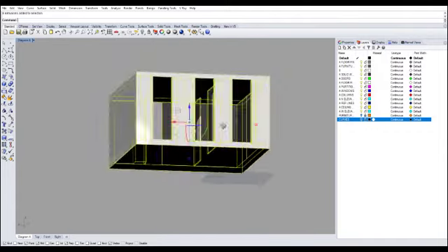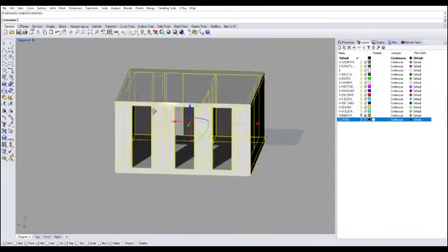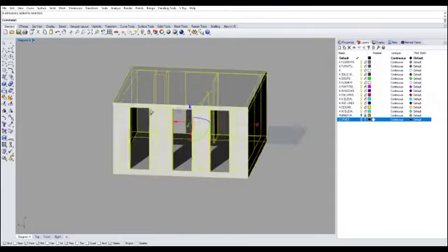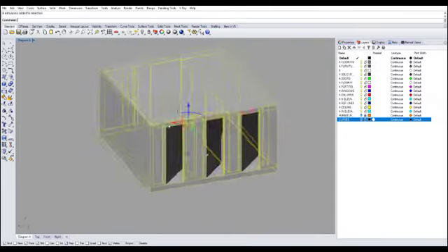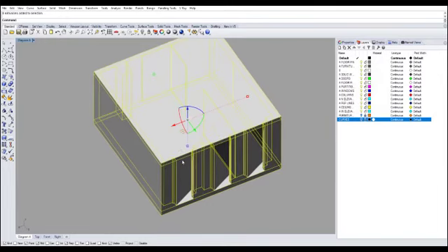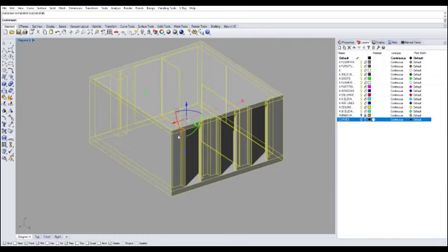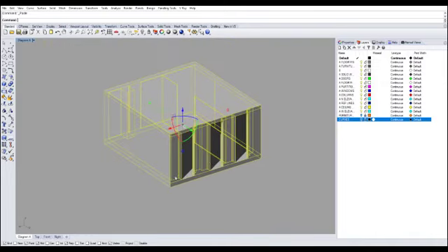So make sure to select all your 3D geometry, because we want the duplicate of everything. It looks like it's completely selected. I want you to copy, Control C, and then I want you to paste, Control V. Now again, it looks like it did nothing, but it really did paste it onto this exact area. Do not, under any circumstances, start clicking your mouse. If you do that, you're going to lose the selection.